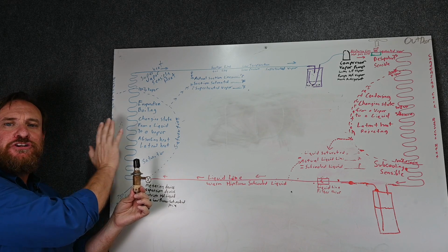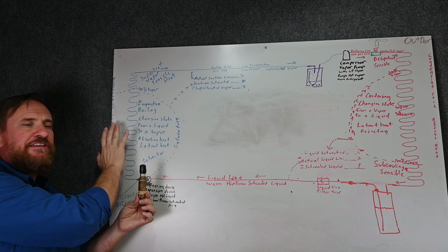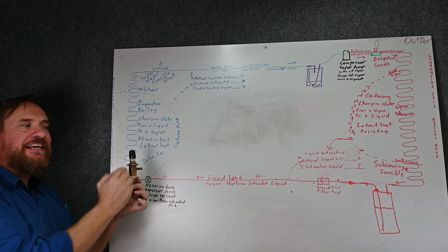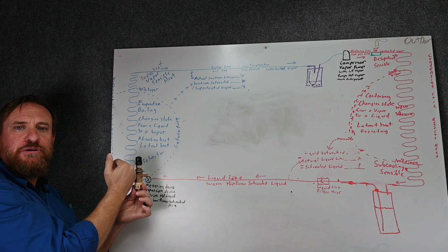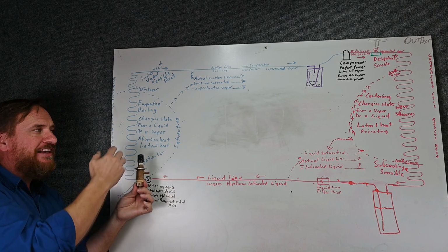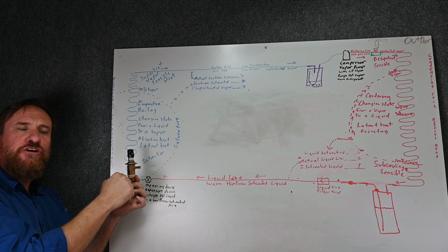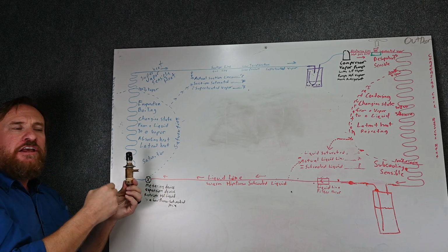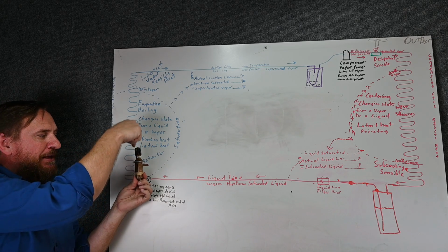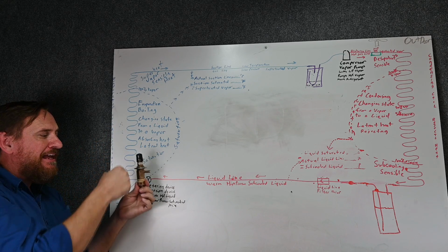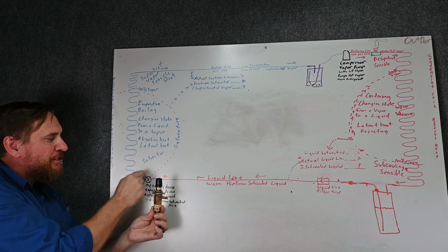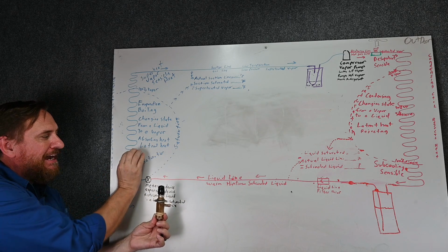The return air temperature goes up. Now typically when the return air temperature goes up, the suction pressure is going to go up also. But this metering device is going to keep the suction pressure at 121 psi gauge. So what it does is this metering device closes. As the pressure is trying to go up, this metering device closes and lets less refrigerant in. So it's keeping it at a 40-degree coil, but only where it's saturation. Because this valve is closing down, I end up with less liquid refrigerant coming into my evaporator coil. So my saturation may only be right here.